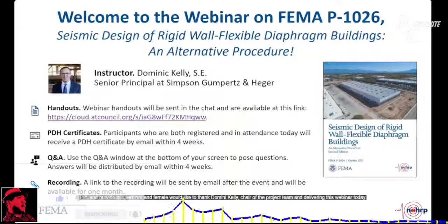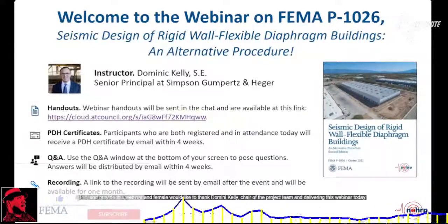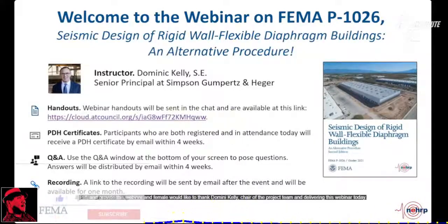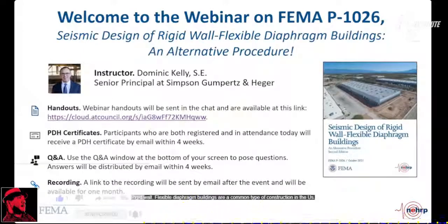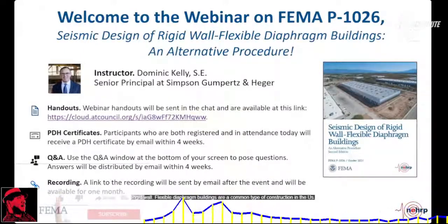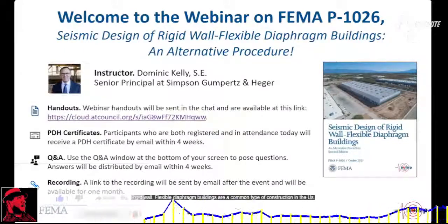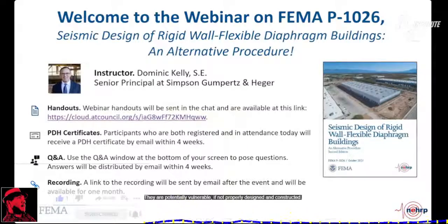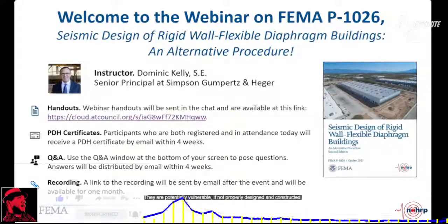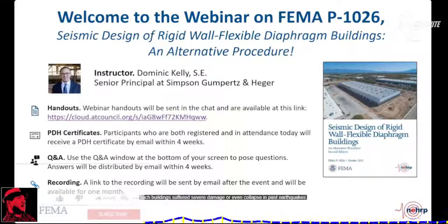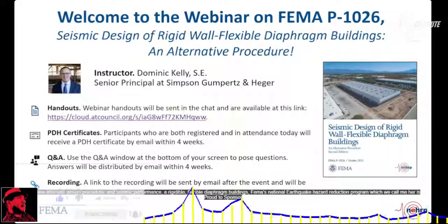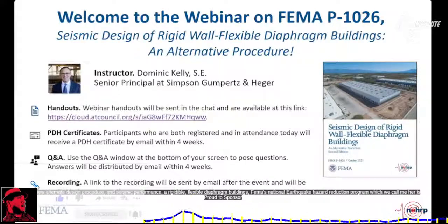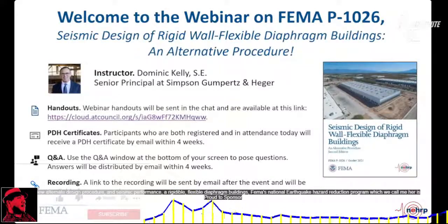And FEMA would like to thank Dominic Kelly, chair of the project team, for delivering this webinar today. Rigid wall flexible diaphragm buildings are a common type of construction in the US. They are potentially vulnerable if not properly designed and constructed. Such buildings suffered severe damage or even collapse in past earthquakes. The new alternate design procedure improves seismic performance of rigid wall flexible diaphragm buildings.